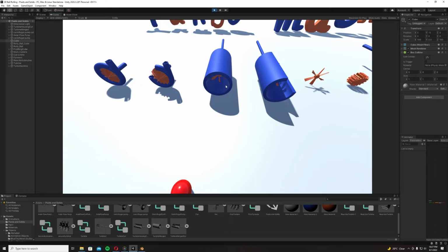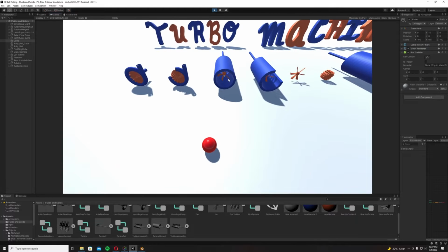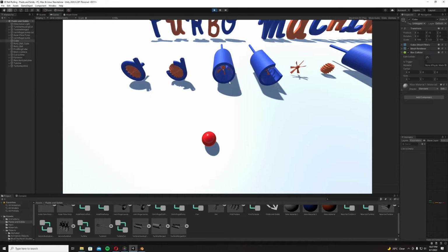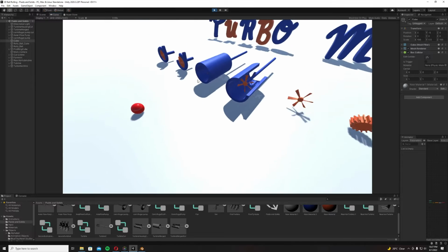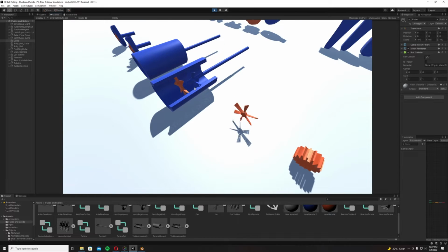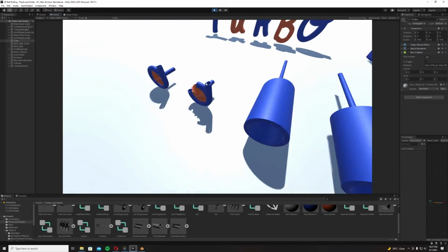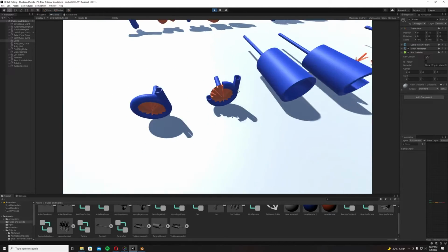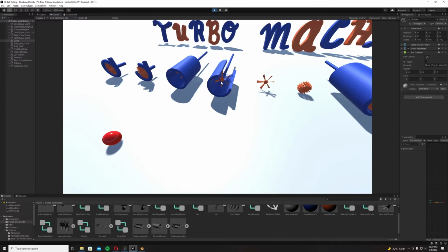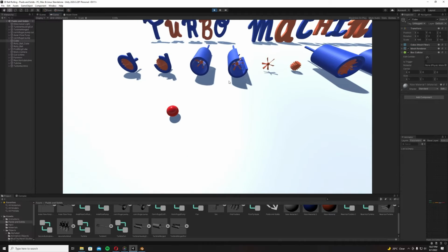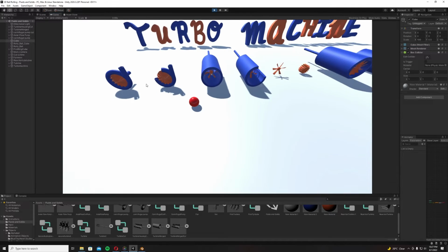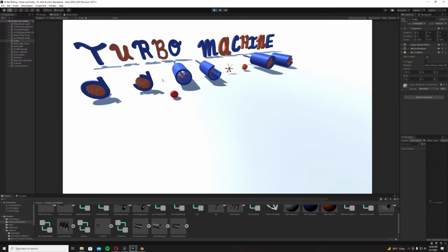Next up, we have the axial flow pump, and how this works is it basically has a propeller at the front, and what that's doing is pulling the liquid back, and then behind that, you tend to have fixed stator blades, and those just help with the flow. And it's important to note that in all these models, these little tubes coming back are the drive shafts. And this pump operates best at low heads and high flow rates.